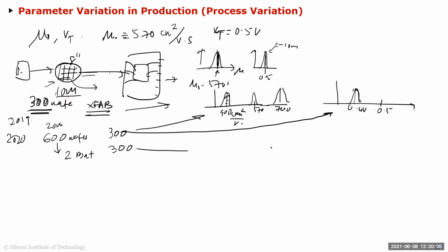And then I take this 300 batch and I start measuring all the 10 million chips, and all of them now are higher actually. They're like 0.6 volts, let's say. Okay, they have some local variation, but they're around that 0.6 volts. And this is what's called the process variation.